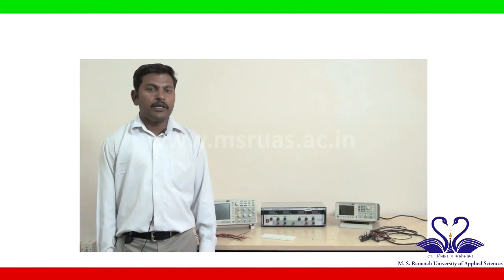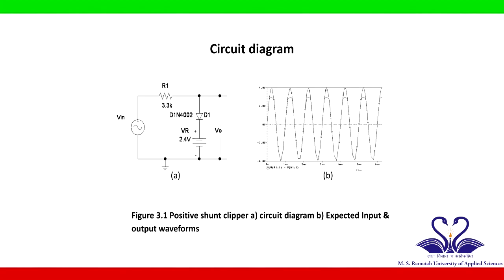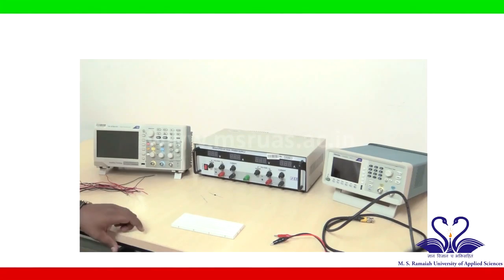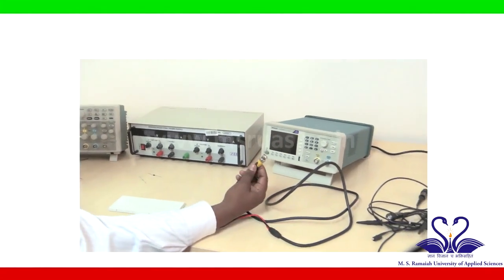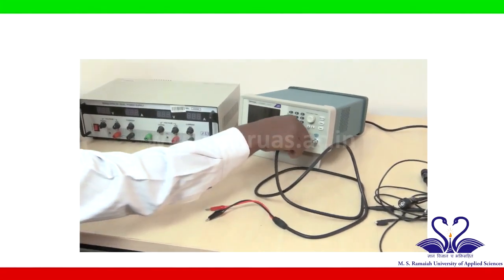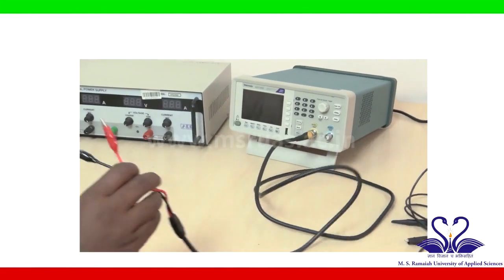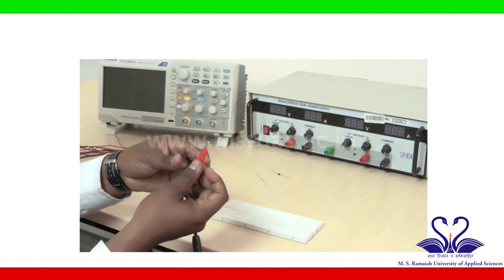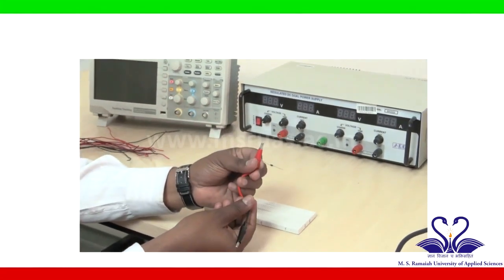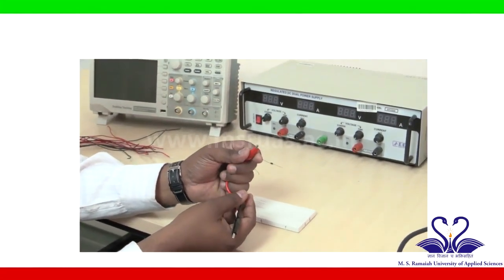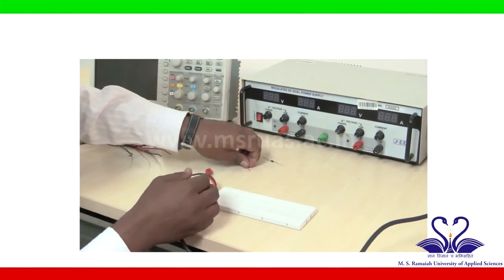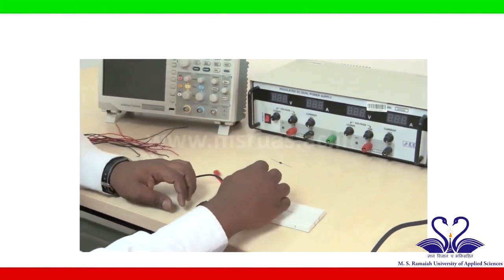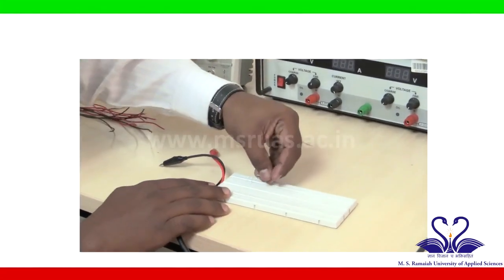Let us begin with the circuit connections. Positive shunt clipper circuit connections. This is a probe. I will connect to a function generator, and this function generator acts as an input voltage to the clipper circuit. This is the positive terminal of the input voltage, that is V in. This is connected to the resistor one end. I will connect the resistor in a breadboard.